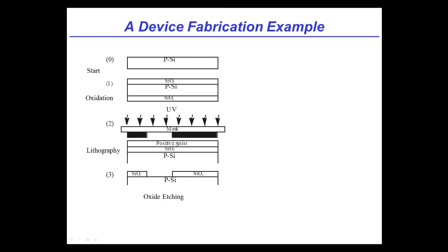And then what we're going to do is use that photoresist as a protectant for etching the silicon dioxide. Remember, we covered that in another slide. The photoresist will protect all the regions we don't want etched, but wherever we exposed and the photoresist was removed, that area will get etched in the etchant. And so we'll be left with silicon dioxide everywhere but that little window.